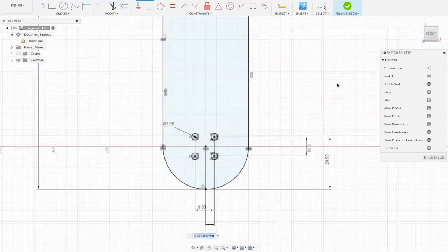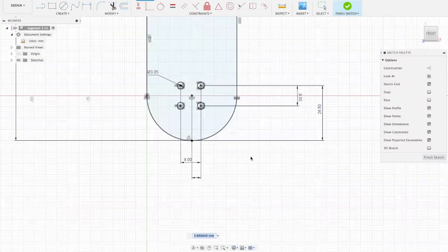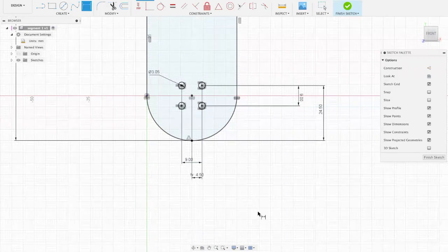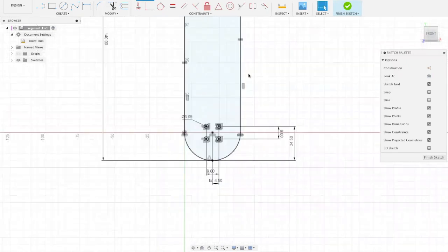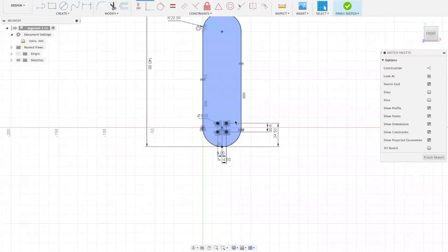And I'm going to set it equal to 9/2. And the reason for that is that the distance between these 2 bottom ones is 9, and we want it to be that over 2 basically. And a good thing you can do is select an already existing dimension and then do math with it. So I'm going to do the 4th dimension divided by 2 by just clicking on that dimension. And this is good because if I change this to 10, it will automatically change to 5. I'm going to keep it as 9 though, because that's the value we want.